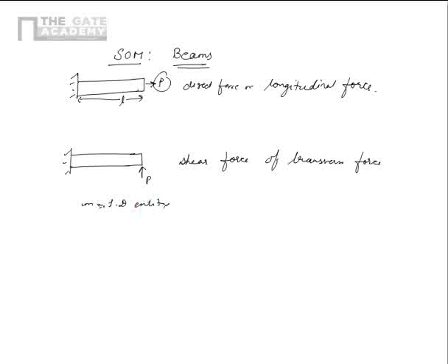Now, what is a one-dimensional entity? One-dimensional means that only the length of the beam is of significance as far as the governing equations of deformation and reactions are concerned. The area of cross section of the beam, let's say it's a rectangular beam like this or a circular beam like that, that area doesn't play an active role in giving the reactions or displacements, etc.